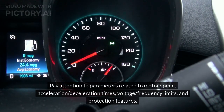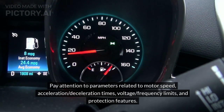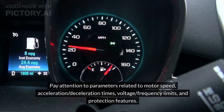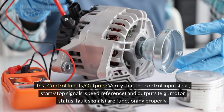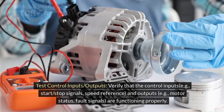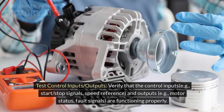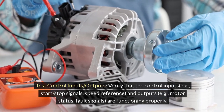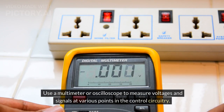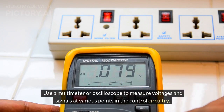Pay attention to parameters related to motor speed, acceleration, deceleration times, voltage, frequency limits, and protection features. Test control inputs and outputs. Verify that the control inputs, e.g., start, stop signals, speed reference, and outputs, e.g., motor status, fault signals, are functioning properly. Use a multimeter or oscilloscope to measure voltages and signals at various points in the control circuitry.